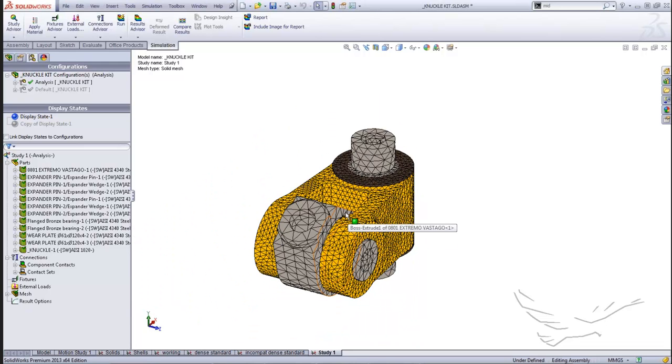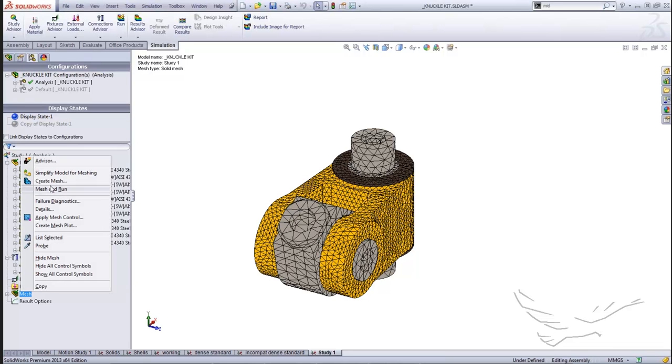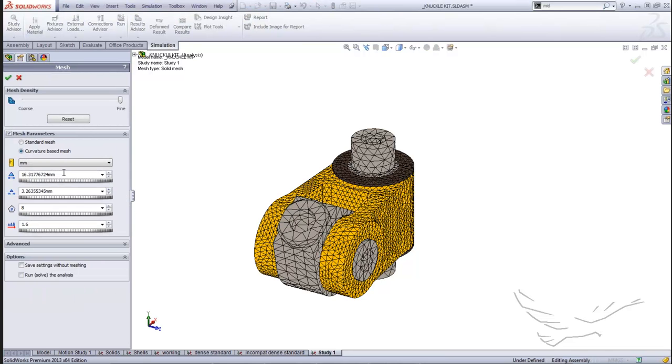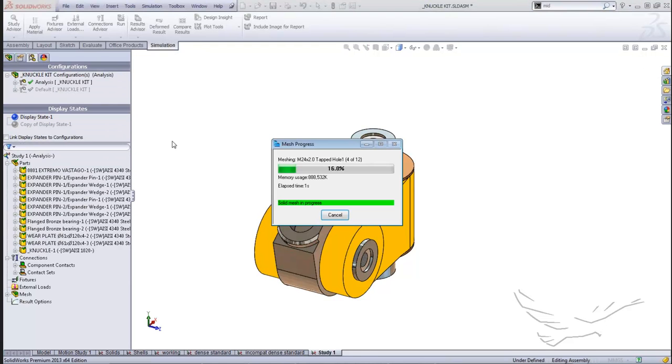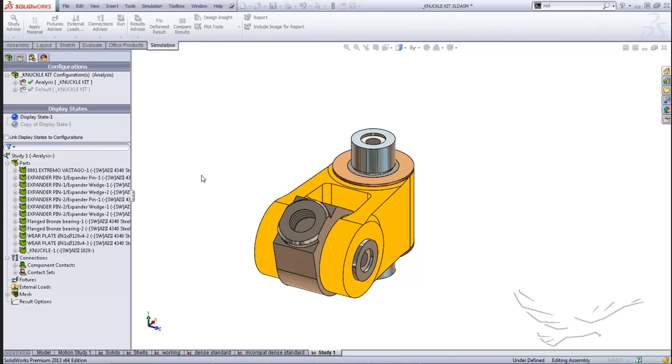The other way of resolving this issue is, again, through the trial and error process, to search for a set of element sizes that work. So the 16 and 3 didn't work. Maybe we try a smaller variation of that, right? So I can try something like 10 to 2 and see how that works. I could also try and play around with the element ratio.